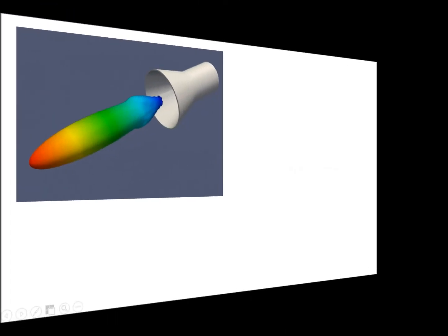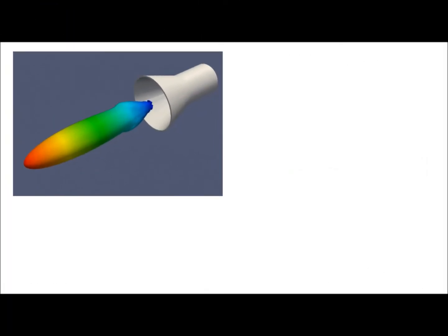So now that you've seen the prototype and you have a basic idea of how the structure looks, I'm going to run you through our implementation in OpenEMS. So I'd like to direct your attention to the screen. Since we chose a dielectric resonator antenna to simulate in OpenEMS, we used the conical horn tutorial file as our template. The template seemed the most similar to the DRA at the time. We hoped that our template would need some simple changes and would be a suitable basis for our DRA. The necessary changes ended up being slightly more complex than anticipated, but the file acted as a valid template. This was especially true in the case of the code for a far-field graph.